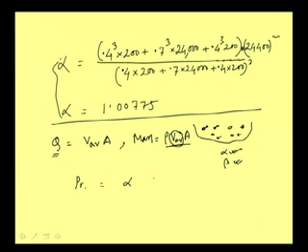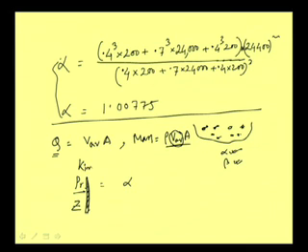The reason is that when we are calculating pressure energy, or the potential energy Z, velocity is not coming into the picture. Velocity comes into the picture only when we are talking about kinetic energy, and that is why this value of alpha comes only when we are talking about kinetic energy. In the other cases these coefficients are not there.